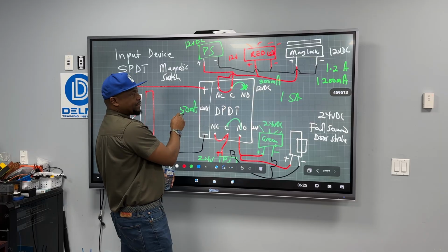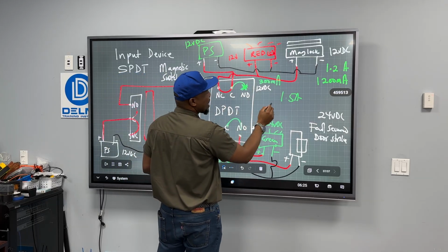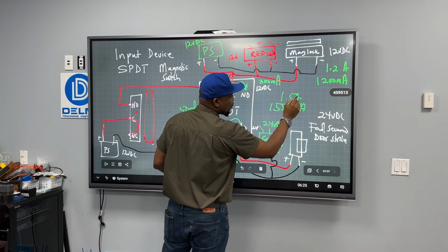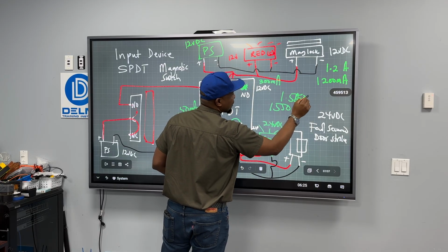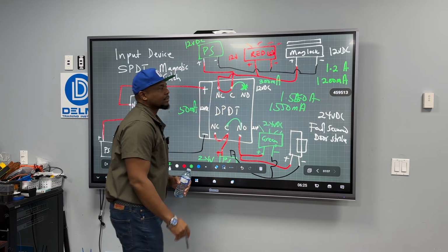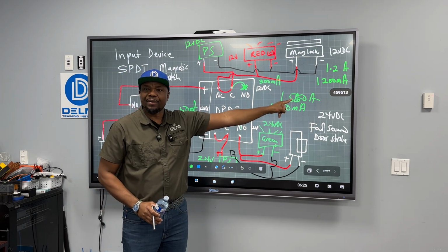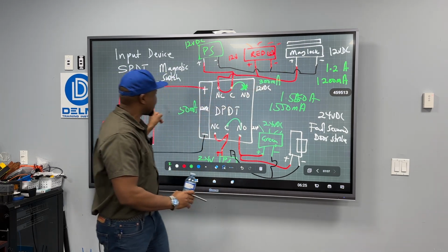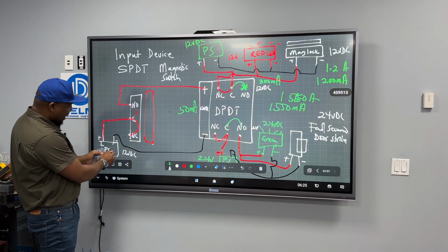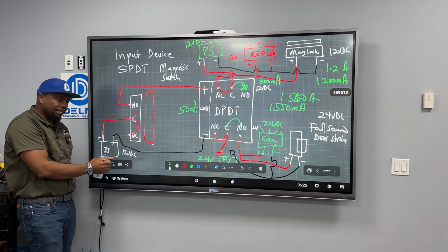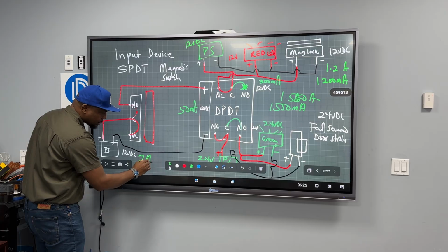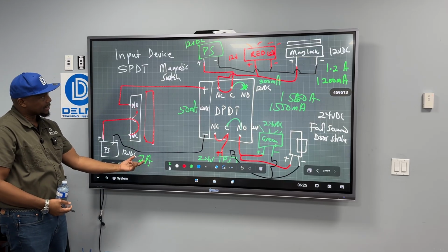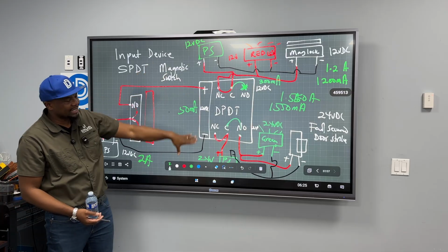Don't forget we have 50 here. So it's going to be 1,550 milliamps. That is the power that is going to be drawn by all these devices together. So when I pick a power supply, I want to pick something like 2 amps, rated at 12 volts. So now with 2 amps, I'm able to power up this guy here.